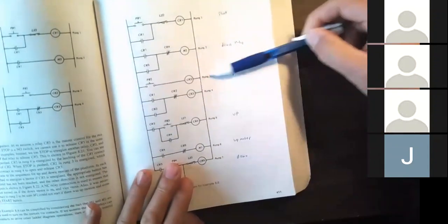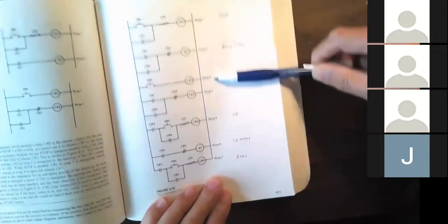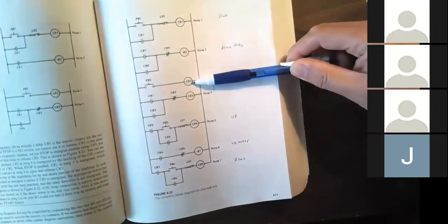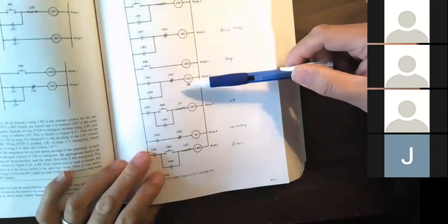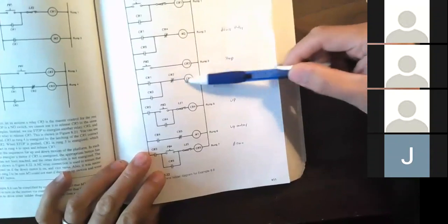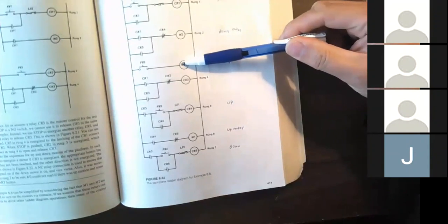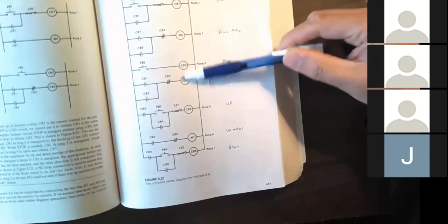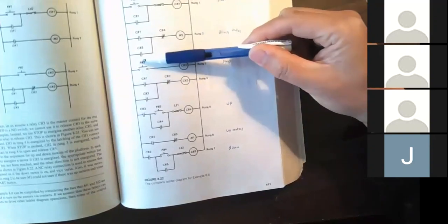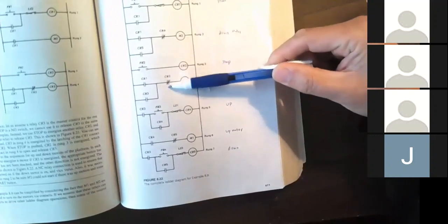Let's look at the stop button. This is a stop button. The stop button will energize CR2. What CR2 will do, it will disengage CR3. That's what CR2 will do. So the stop button does not have memory. Instead, it will kill CR3. That's the memory. So CR3 is the memory. Remember, everything is running until we push the stop button. When we push the stop button, it will kill this memory because CR2 will open.